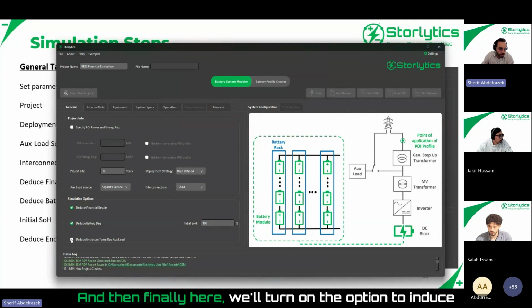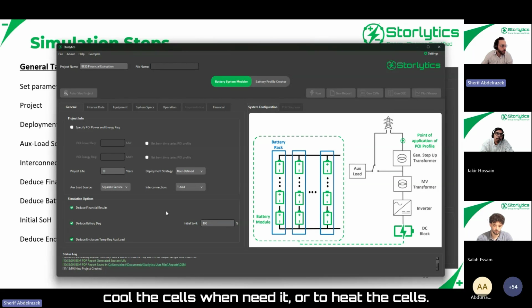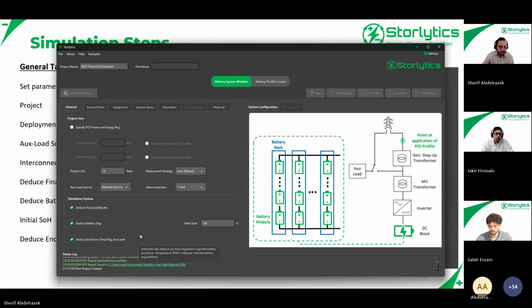And then finally here we'll turn on the option to deduce enclosure temperature regulation auxiliary load calculation. And what this does is it allows the simulation to calculate what the auxiliary load will be, which is primarily, in lithium battery cases, HVAC load to cool the cells when needed or to heat the cells. And if your project is in a cold environment, you'll need to heat the cells. So this option allows the simulation to do that automatically.